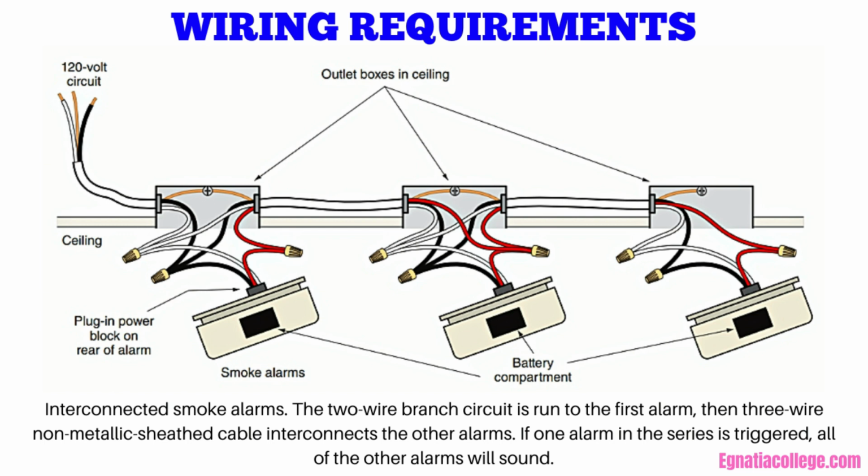All new residential construction requires an interconnected smoke alarm on each level of the home and near the bedrooms. If bedrooms are located at opposite ends of a home, it may be necessary to install more than one alarm on a level. Interconnected smoke alarms have one white wire, one black wire, and one red or yellow wire, which is used to interconnect them. Refer to the figure for wiring these devices. Interconnection of these units can also be wireless.